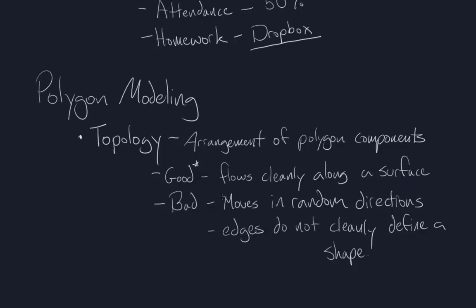However, if you are creating an object that is completely rigid, that is never going to bend and never going to flex, then the rules of topology are suddenly not as important. Because in those cases, you don't have to worry about deformation. You just need the object to look good. So you have to keep in mind what it is you're modeling for. I've created models that are sent out via maybe SolidWorks or to a 3D printer, where really all you need is a bunch of triangles. And the final result, the topological flow, is nowhere near as critical as just making sure that everything is nicely shaped and solidified. So it depends on what you're up to.